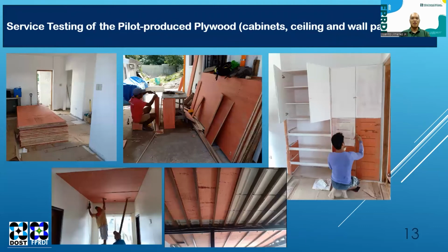The pilot-produced plywood were tested in actual construction in partnership with a construction company and a house owner operator to determine the workability and performance of the produced plywood. The pilot-produced plywood will be observed for 5 years to determine its termite performance in service, as well as the bond integrity, especially the plywood used for ceiling.